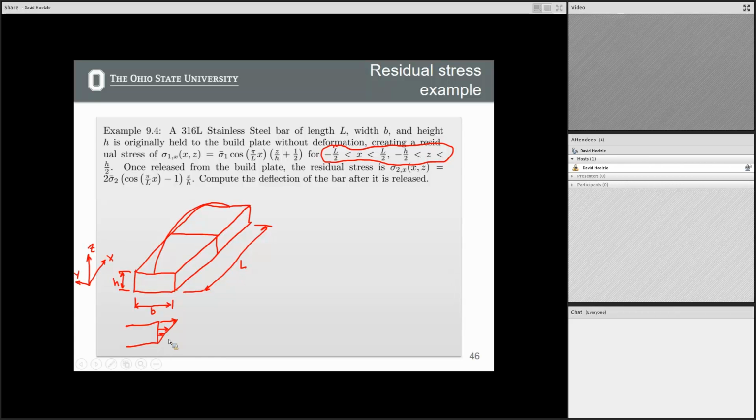And this is approximately corroborated with experimental data that our group and other people have taken, and also matches some of the really basic residual stress theory in terms of how thermal contraction and expansion yields residual stress in a part. It has a fairly linear relationship. And so that would be this part here, where keep in mind that z equal to 0 is all on this neutral axis. Or not neutral in this case, but the center of this beam in terms of a moment of inertia perspective. Okay, so that's what this function is basically saying.